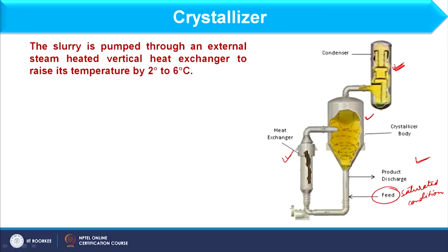When the feed enters, it first enters through this pump to this heat exchanger. And in this particular heat exchanger, the temperature of this feed is increased, and that increase is usually not much, it is usually 2 to 6 degree increment.